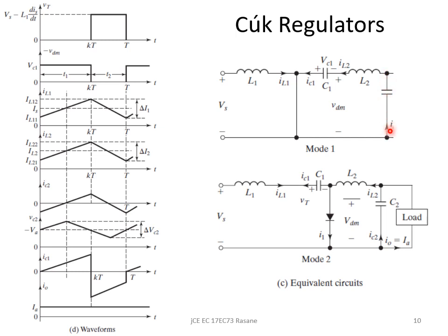Next is the ripple voltage across this capacitor, VC2. So it will always develop a ripple voltage, right? It will develop a ripple voltage, and that ripple voltage will be from minimum to maximum value, right? And it is called the ripple voltage VC2, and its average value is going to be the DC voltage that is coming across the load, because it is in parallel with the capacitor.